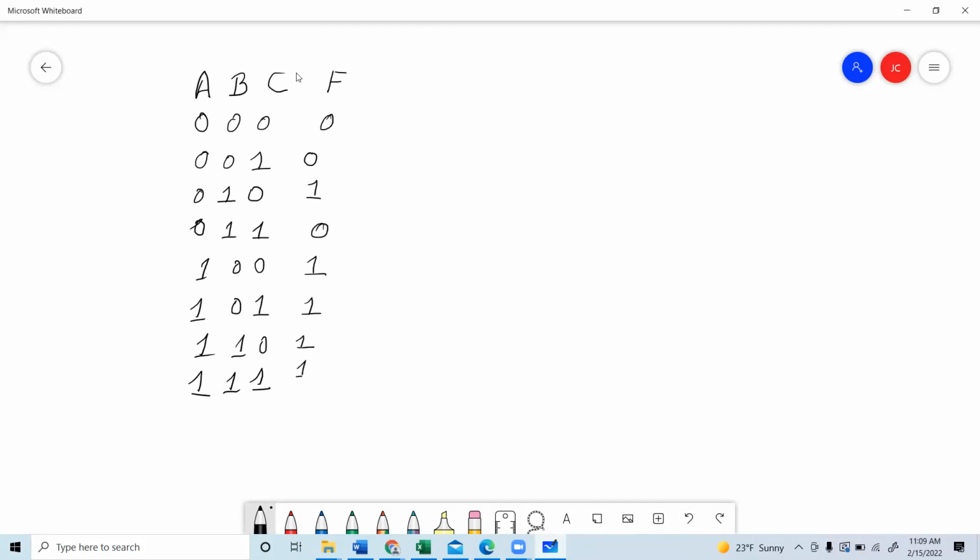The final circuit I gave was F equals A plus B C prime. I said that I go to school on a Sunday. A means a Sunday, or a holiday, if there is no exam tomorrow or something like that. That's why I put A, B, C. You can give any analogy. I just follow the same analogy for this circuit, but we are not given the final expression here, so we're going to build it from the truth table.